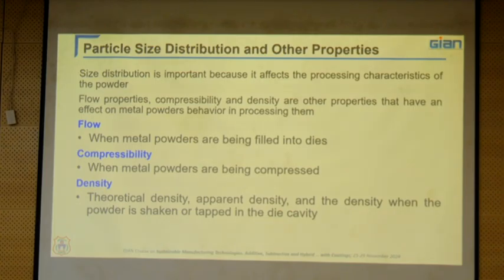Compressibility means, when you apply load onto the powder poured into a container, to what extent it is able to compress. And when we come to density, bulk density is different, theoretical density is different, apparent density is different, and grain density is different.